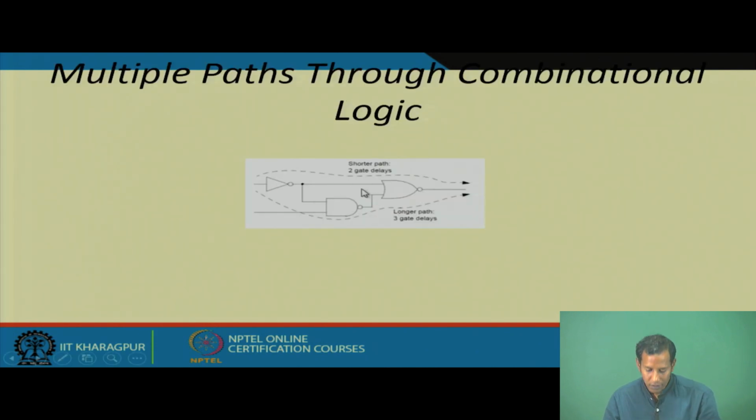There may be this kind of situation, where more than one path will be available from input to output, and the timing information of every one of these paths you have to calculate using static timing analysis. If you miss any one of these paths and it is associated with a violation, then your chip will not work, it may fail to perform successfully. Okay. Then all the money and all the effort you have put in will be in vain. So, that is why we double check, to make sure that the IC we have designed is working perfectly fine.